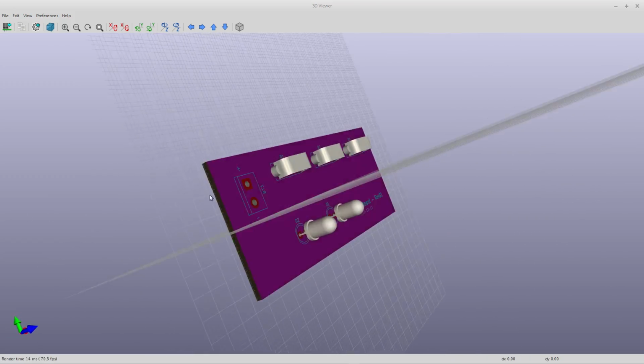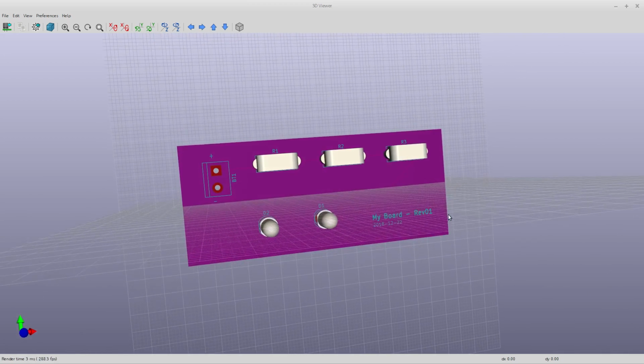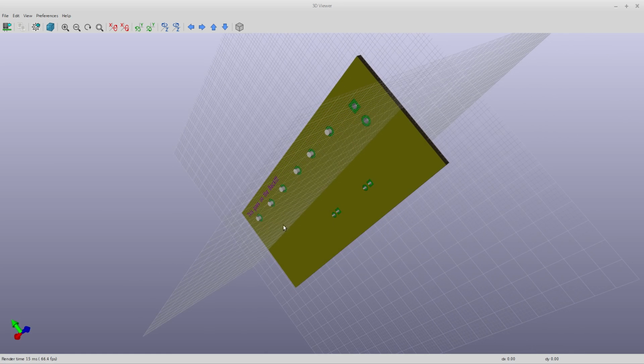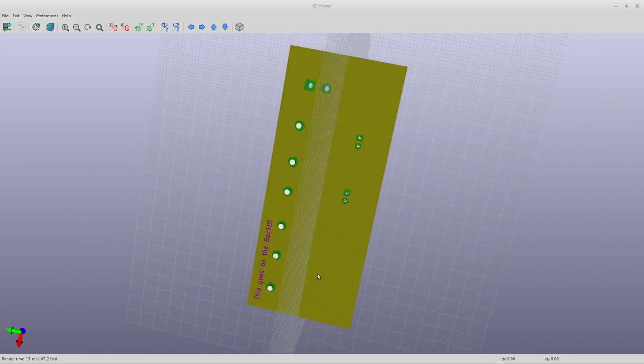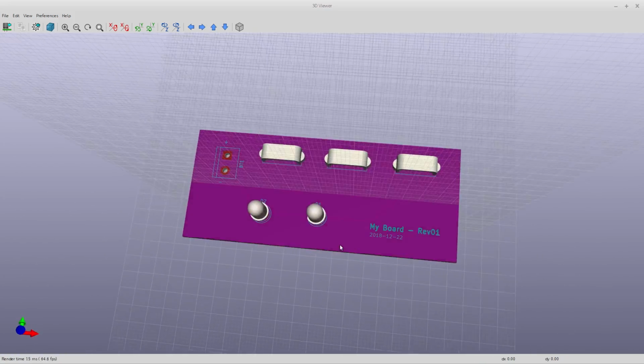Adding in test points is a great thing to do so that you can see what you're supposed to be getting for signal and power or whatever at different points. And having all your test points around, you could say like we got TP1, TP2, TP3, TP4, right? Maybe on the back here you write TP1 is power in, TP4 is signal X, TP3 is signal Y or whatever, right? And or what you're supposed to be getting there, okay?